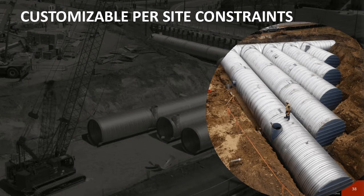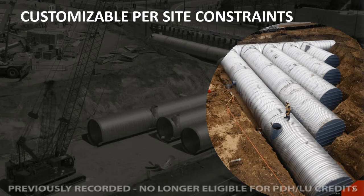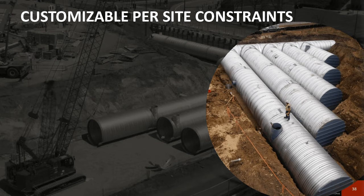Here's just another photo showing some of the customizable features of corrugated steel pipe. Here we've got a manifold and a number of pipes that are coming off of it, and the pipe lengths are staggered to create a geometry that again fits the site conditions. So this is actually very easy and economical to do with corrugated steel pipe. With a lot of other systems, it's just more complicated in order to get it into some of these more specific geometries.